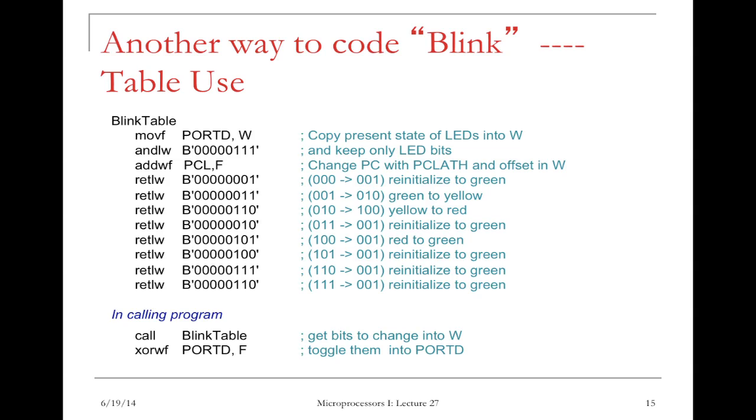So when the microcontroller tries to execute this ADD instruction, the PC is already pointing to the next one. It's always pointing to the next one, next one, because the microcontroller needs to know which one is the next one. It already knows, oh, I'm going to execute this one, but what is the next one? This instruction itself will change that pointer because we're adding a value, which is 1, onto this PCL. This is the PCL, part of the PC. So it will change this pointer to here. The microcontroller just needs to know, oh, that's the next one. This is no longer the next one. This is the next one.